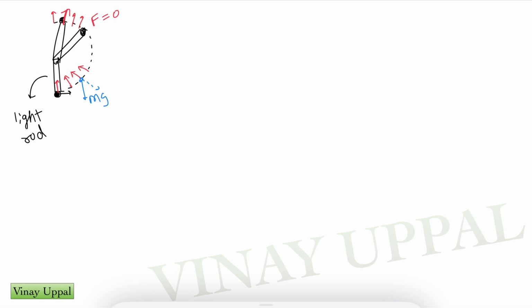Now this is the case in a constrained circular motion. In a constrained circular motion, the particle can experience this sort of an outward radial force by the rod or by the pipe. But suppose you have a string, in the case of unconstrained, the motion will be exactly the same as the constrained motion until the point the force becomes 0. The force by the rod, once it becomes 0, it can change its direction.